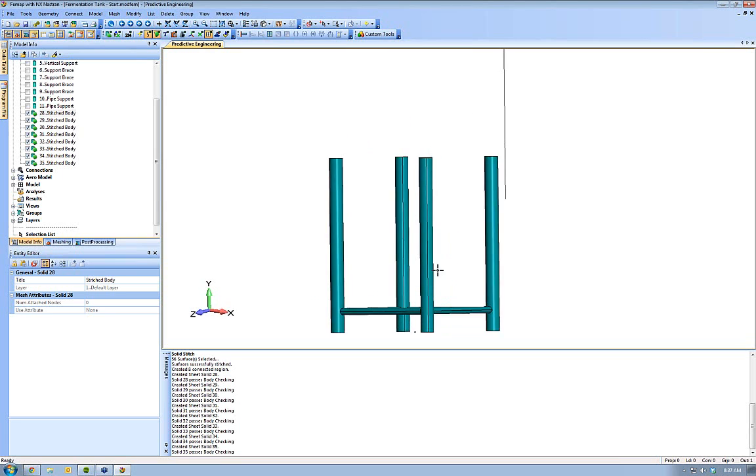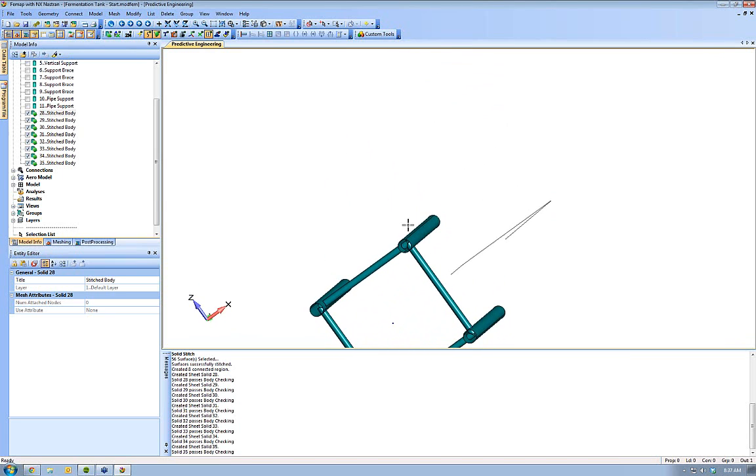This is called a non-manifold intersection. And the way we always describe it is kind of like letters of an alphabet. An L is manifold. It's just a simple 90-degree connection. And I'll draw this out on the screen here. So there's an L, and this is our connection. But something that's non-manifold would be something like a T, where at this intersection you're connecting more than two surfaces. There are more than two surfaces sharing a curve. And you can imagine that these intersecting cylinders down here are even more complicated.